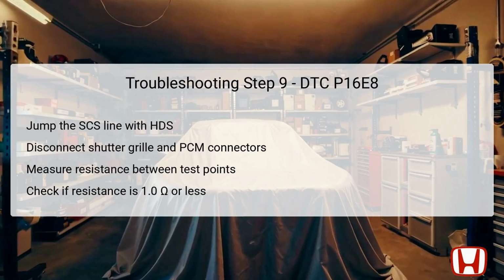If it meets this criterion, LIN communication is deemed functional, and the technician should refer to authorized service information or consider a known good PCM substitution. If it exceeds this limit, repair measures should address the open wire connection along the circuit.